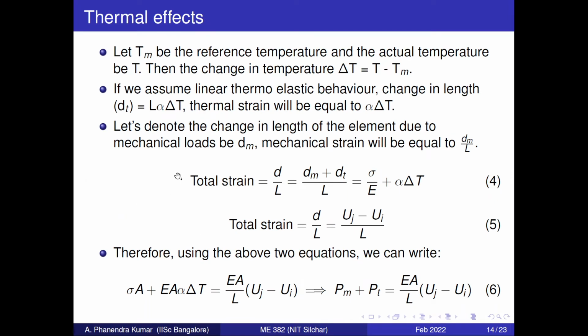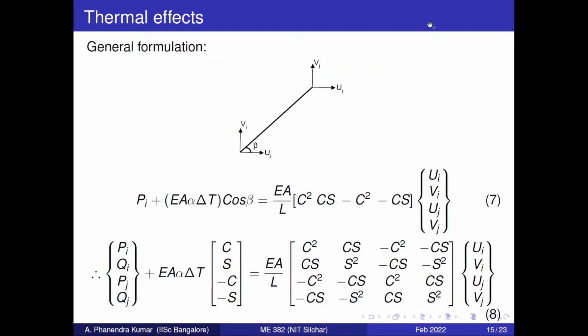So we know how we can evaluate by displacing each degree of freedom and obtain the final stiffness matrix of the structure. Similarly, if we have an arbitrary element which is making an angle beta, we will find out how the formula will be generalized for that case, for an element making an angle beta with the horizontal.